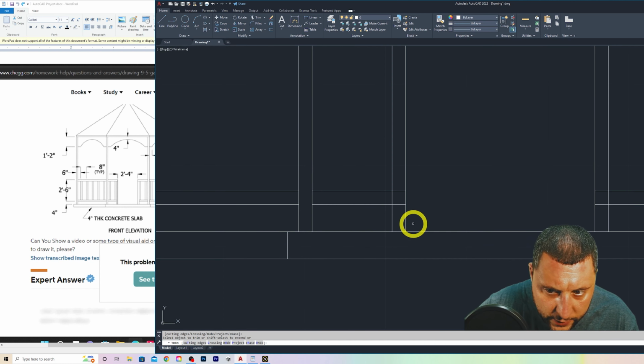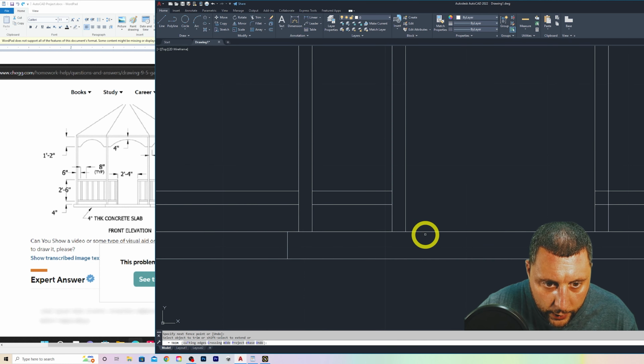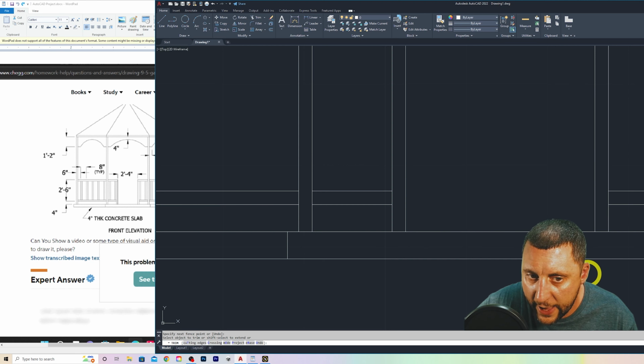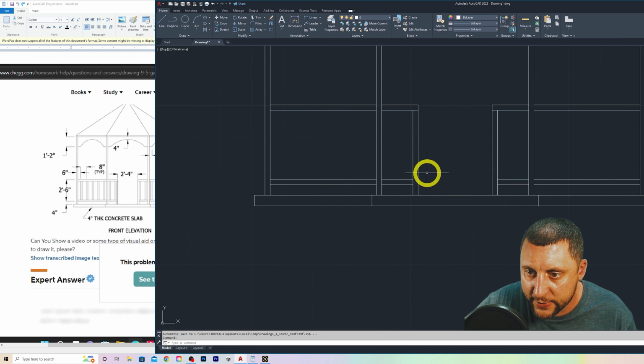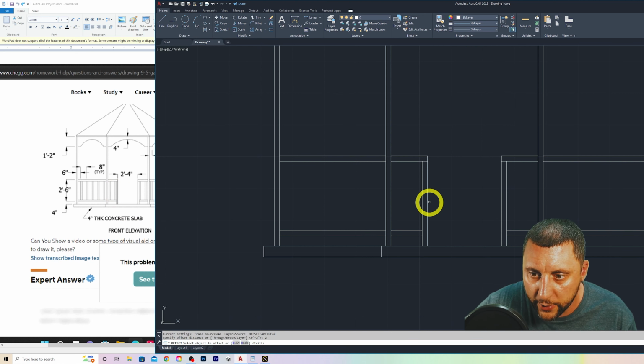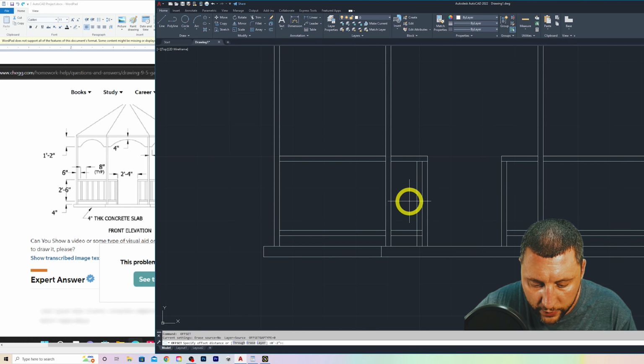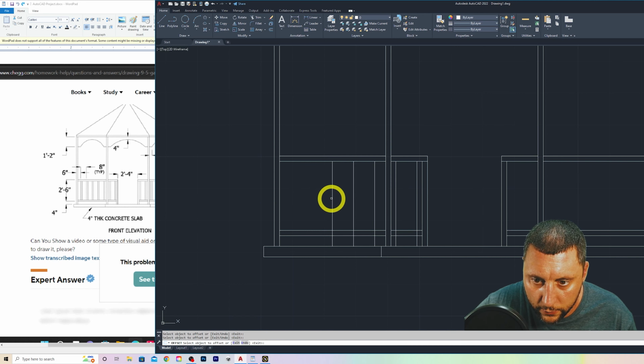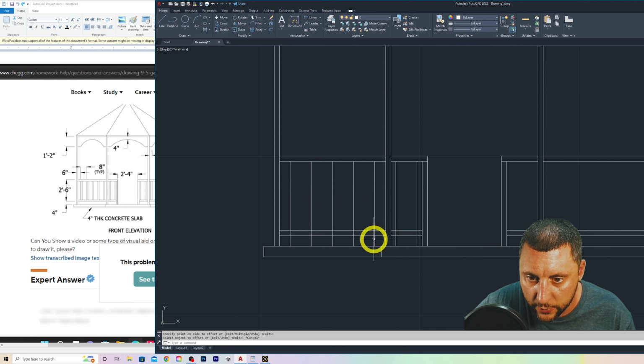Also, this is going to be wide open like that. And now we've got 8 inches from the left side of a spindle to the left side of a spindle. Or the end one, from the inside of the 2x4 to the inside of the spindle, is 6 inches. I'm going to start on the inside here, and I'm going to show you that there is a double right here. There's a long one and there is a short one. So that's going to be an immediate offset of 2, then 8, and 8, and 8, and 8, and 8, and 8. You get something like that, okay?